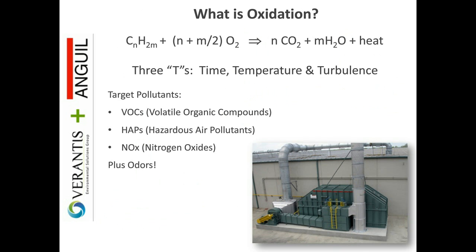So before we actually get into the nuts and bolts of the various technologies, I like to put this slide in here just so we're all on the same page of what oxidation actually is. It's a chemical reaction. Keep that in mind. The definition is you have your hydrocarbon or your solvent or your VOC combined with oxygen. In many cases, oxygen is already present if we're treating an airstream. We add in heat, and the result is the hydrocarbon or the VOCs are broken down into CO2, water vapor,